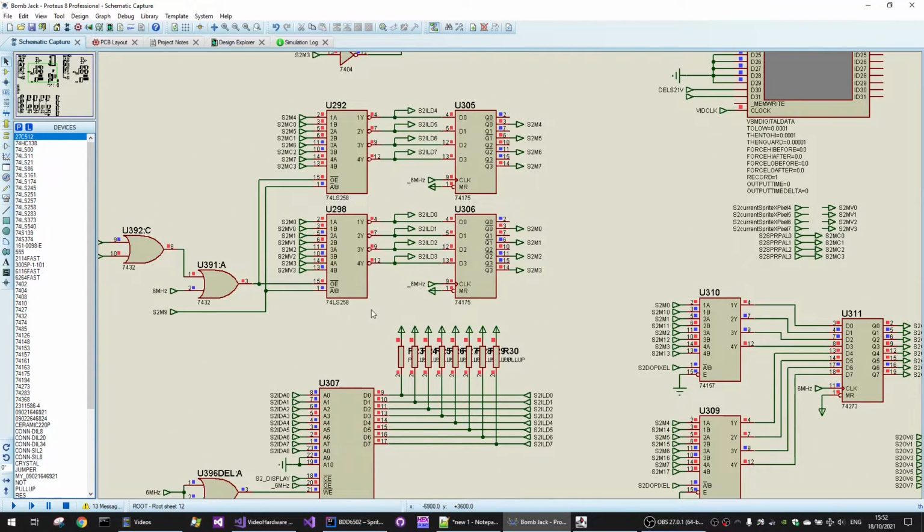And it's actually stamping out an inverted value, because the value is coming through as an inverted value here, but it's also being read inverted from the RAM. So this is a non-inverted value, but internally the RAM holds it inverted. It's just done like this because the logic is a little bit simpler.